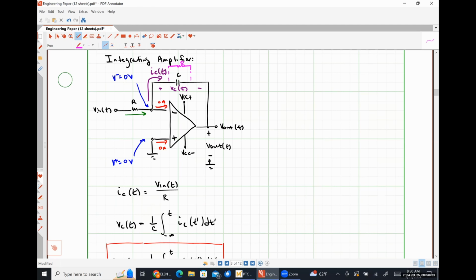Okay, so let's talk about the differentiating amplifier and the integrating amplifier here really quickly, okay? In the context we're talking about today, we use these amplifiers to perform the mathematical operations of differentiation and integration respectively. However, they are also very regularly used in control systems for what's called PID control, so proportional integral differential control. Integrators provide the integral part of that. Differentiators provide the differentiation part of that. So they're part of control systems. They're also very regularly used in communication systems.